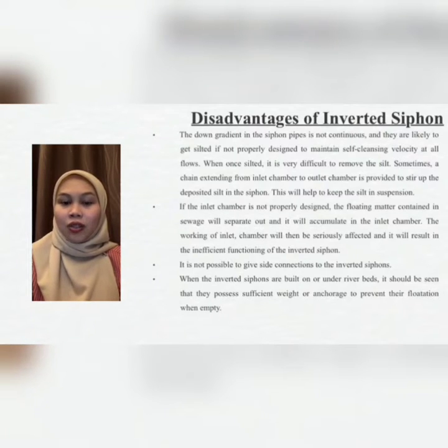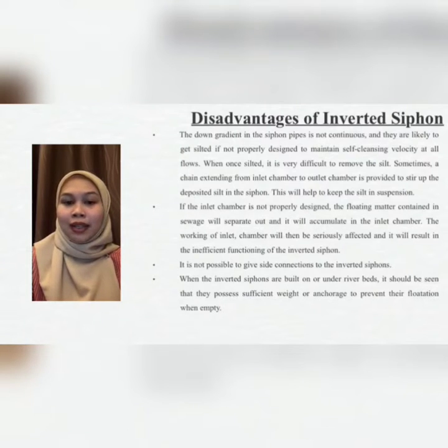Sometimes a channel extending from the inlet chamber to the outlet chamber is provided to stir up the deposit silted in the siphon. This will help to keep the silt in suspension. If the inlet chamber is not properly designed, floating matter contained in sewage will spread out and accumulate in the inlet chamber.